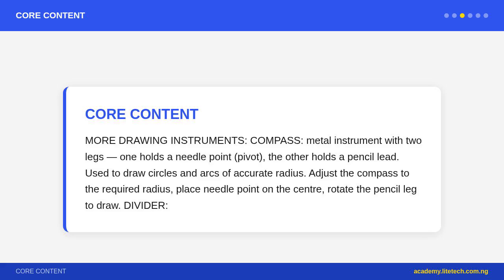Drawing pins and masking tape secure drawing paper to the board. Drawing pins make holes, so masking tape is preferred for quality paper. Eraser or rubber: removes pencil marks, and should be soft enough not to damage the paper surface. Erasing shield: a thin metal plate with cutouts, placed over the drawing to erase one line without accidentally removing surrounding lines. Dusting brush: a soft brush for removing eraser dust without smudging the drawing.